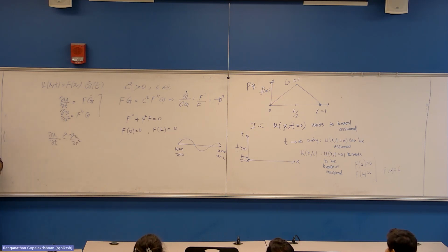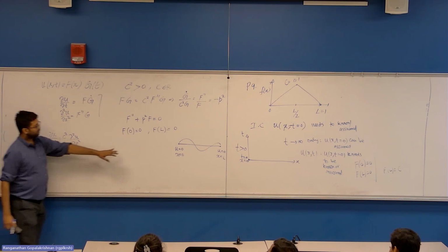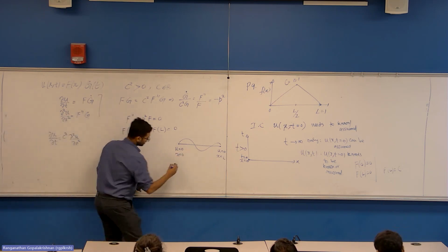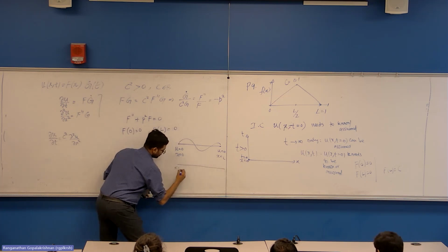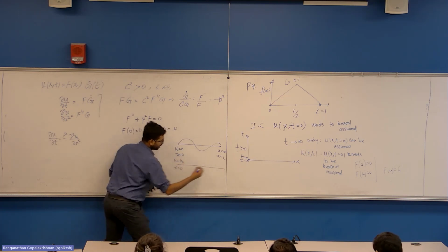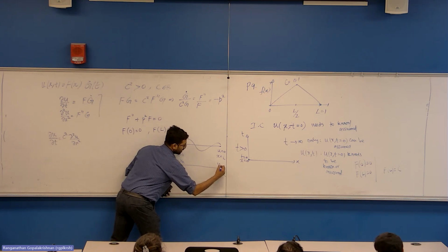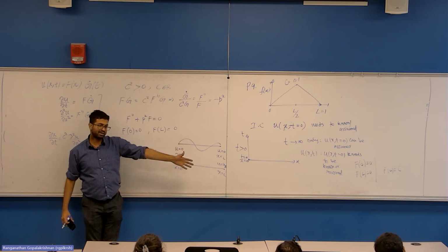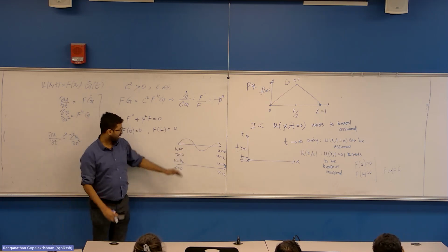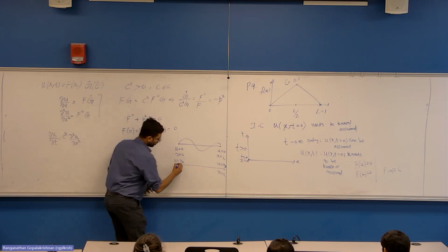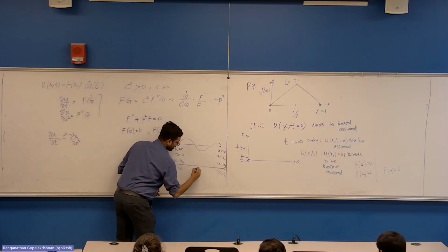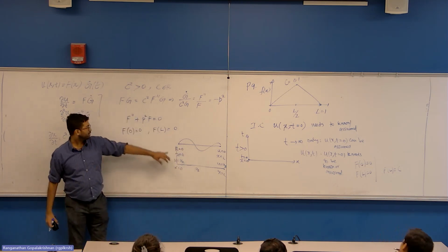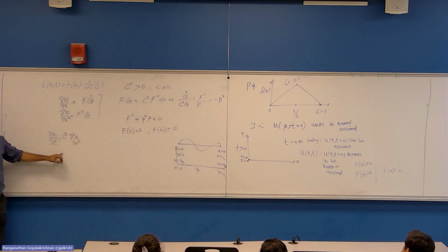This is one possible use. That is, you might have something that is between fixed levels and ask to resolve the time difference. The other case is, if you have x equal to 0 at a certain temperature, I'll call it UA, and the other end at another temperature UB. How does this temperature profile get set up? So you will have an evolution. Initially, the temperature is, let's say, 0 everywhere, or let's say it is just UB everywhere. Slowly, that temperature will start developing. How does it develop? The solution comes from the heat equation.